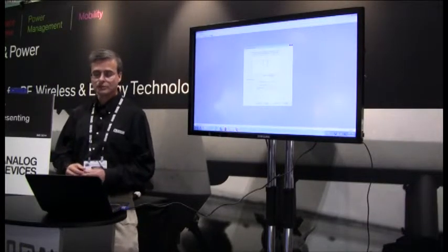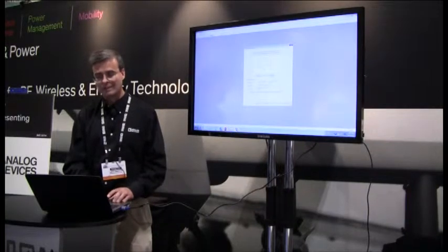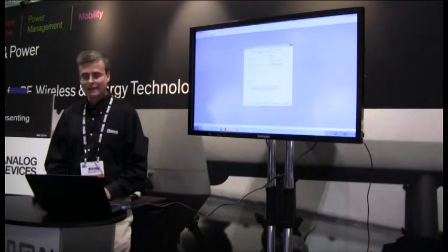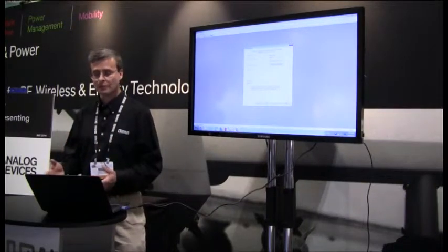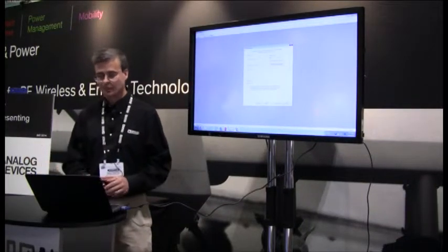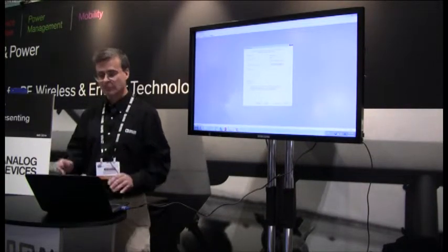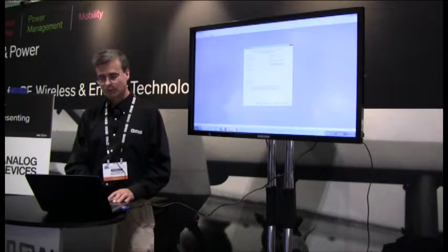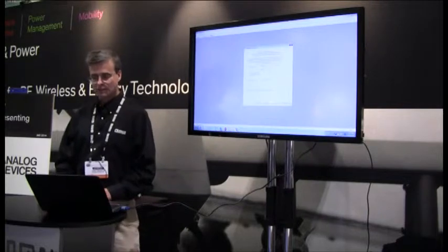You're able to choose your loop filter, and with that you can choose your loop filter topology, including various different active loop topologies. I'm just going to choose a simple one here. Next, you're able to choose whether you want to pull up a VCO from a library, or do a custom type VCO, and we have a whole range of libraries of different VCO vendors that we've included with this program. And I'm just going to choose a custom VCO and use the setup.